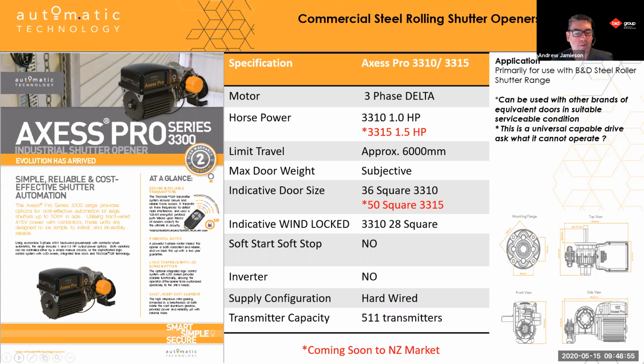And if the 3-phase power is already set up at the specification level and the build stage, that's the unit to use, because it's going to be reverse engineering to get a 240 volt power point set 1 meter away from the unit in the opening after the build's already done. Okay, so it fits a sweet spot, and the range option is very tight, but it covers that, as I said, 36 square meter door and also 50 square meter door.